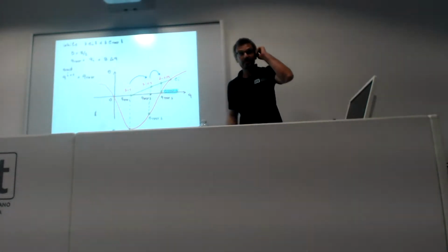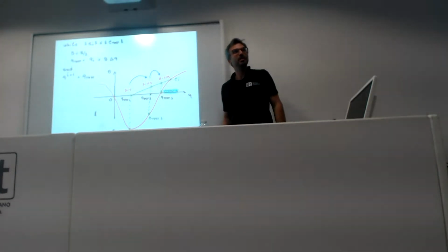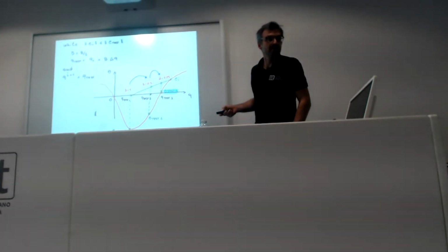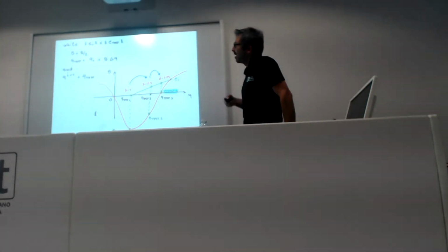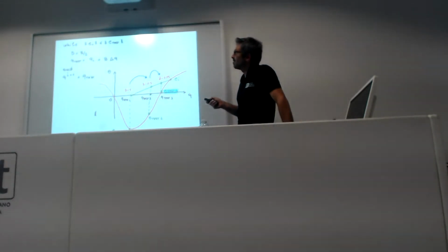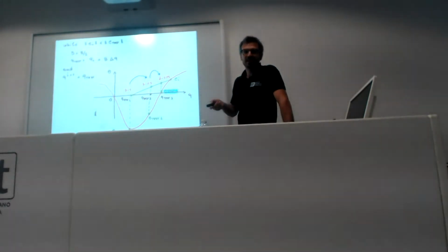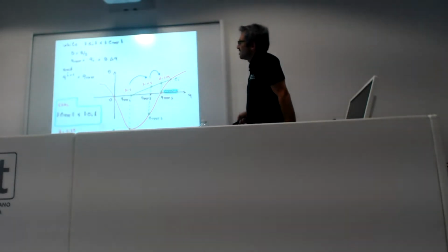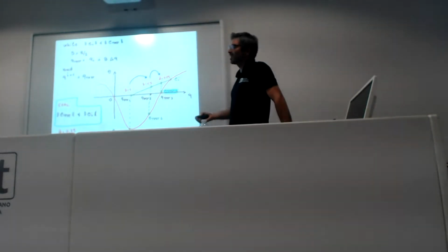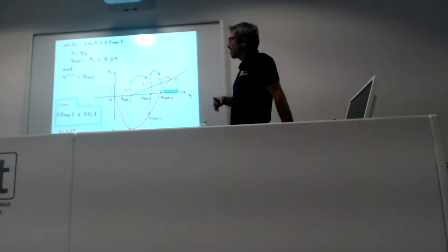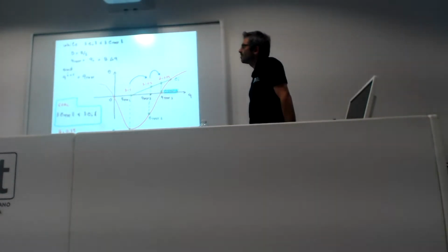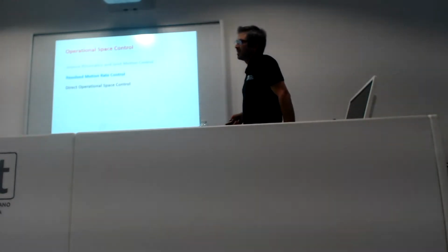For the next step again, starting from 1. Exactly. That's why it's slow. It can be slow because you need to do all this. It's a backtracking that you do inside each Newton iteration. So it can take time to get an inverse kinematic solution. It's generic. It works for every robot, but it's slow.